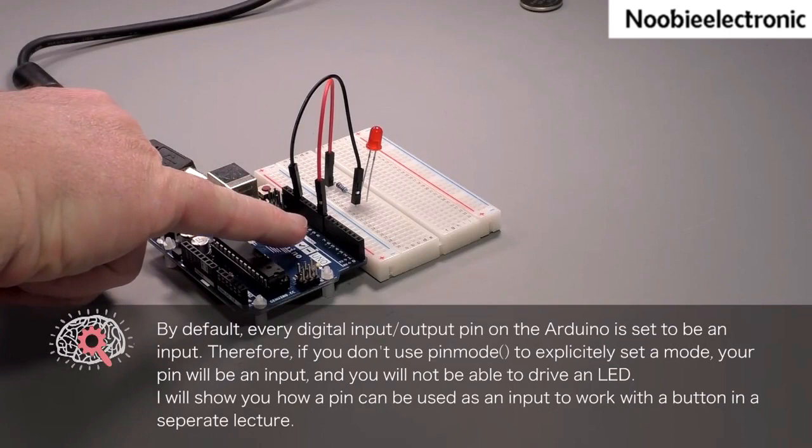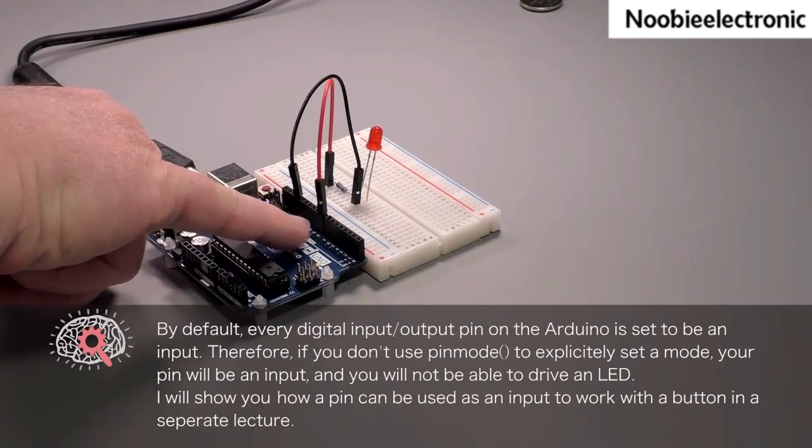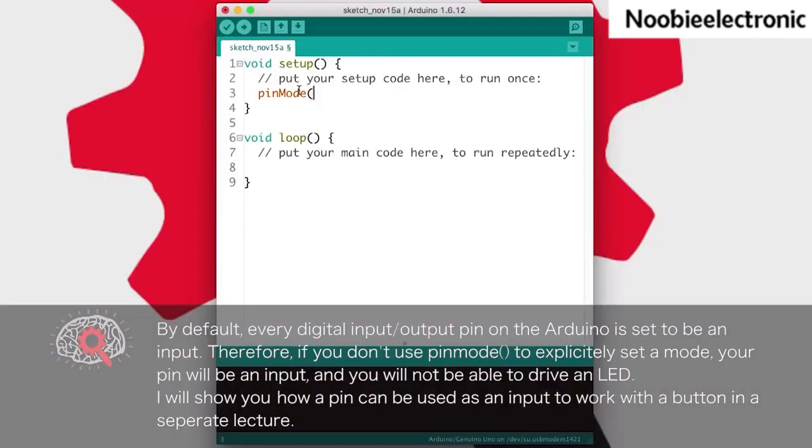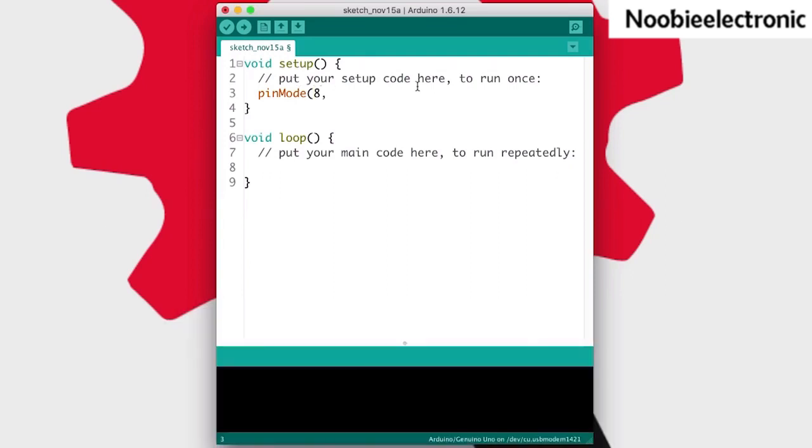In our case, we've got the LED connected to pin number 8. It means that its anode is connected to pin number 8. So here I'm going to type 8. And next, I need to tell in the same instruction, the second parameter, that this pin is going to act as an output. If I wanted this to be reading the state of a button, as we'll see later, then I could have said input here.